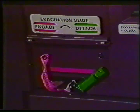These doors are not to be cracked or opened by the flight attendant. Only the agent or caterer may do so. The L and R3 doors are smaller. They do not have slide rafts, only single-lane slides, and in an emergency, they are not air-assisted. These doors have much the same features as the larger doors. There is the arming lever, operating handle, this time with a cover, and a single door locking indicator at the top.